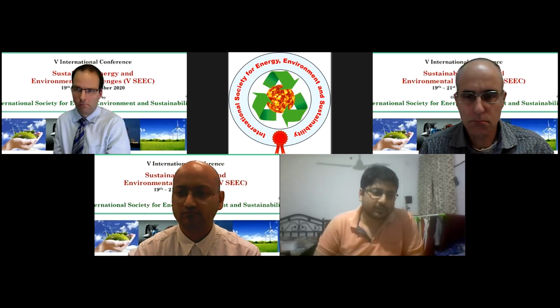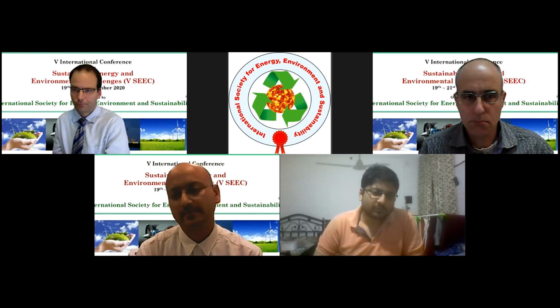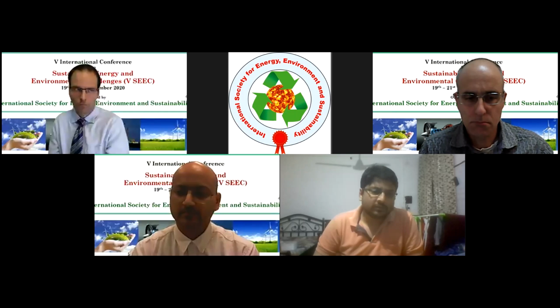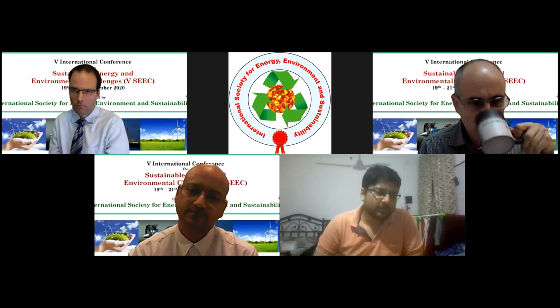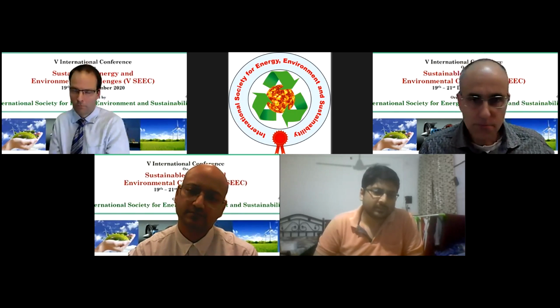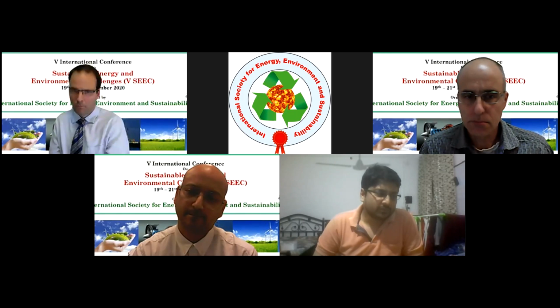Is he looking for resource recovery or something? One of the key issues in RO at home is that the water recovery is very poor, roughly 30% or something, right? So lots of water goes to drain, which is not a very good practice in the long term. Also, it increases the concentration of some pollutants, particularly nitrate. I have read somewhere that it provides some 3 to 5 milligrams per liter of nitrate or something. So that should be looked into.